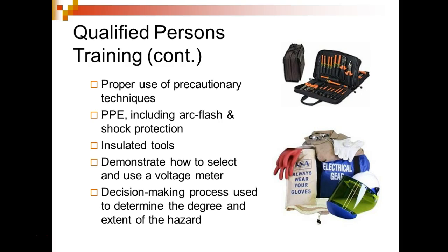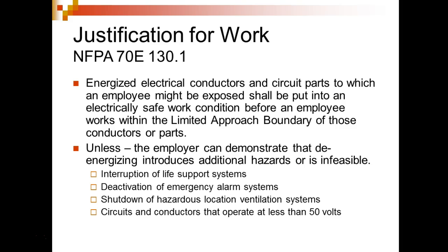If you pop the back of the meter, you'll see the battery and the fuse right there together. Now the fuses and the batteries have got to be separated. In a new meter, the fuses are actually in little indentations, so if a fuse arcs, it won't get into the rest of the meter, right? Does that make sense? There have been a lot of improvements in meters since I've been here.